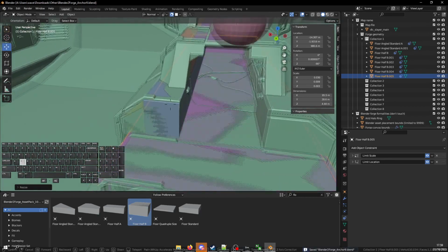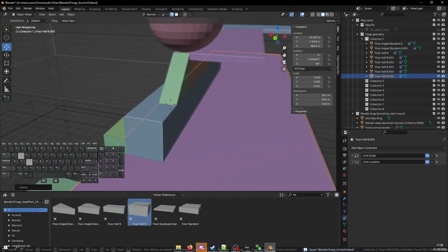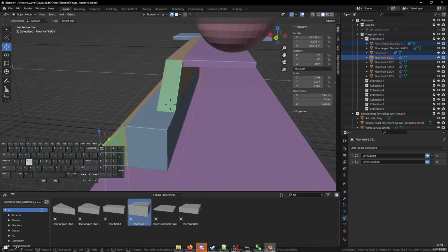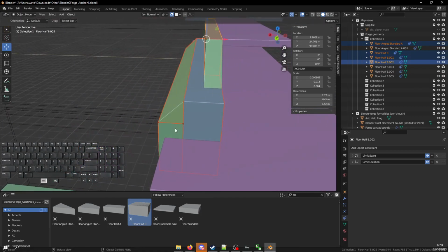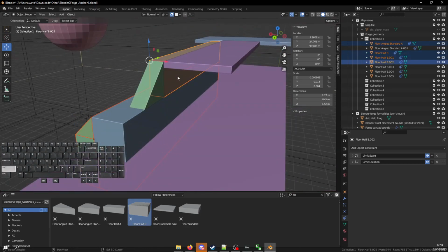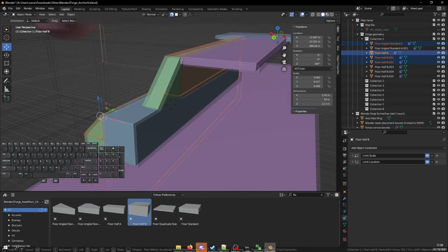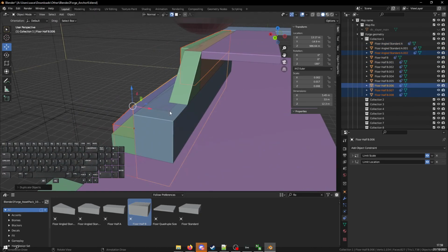Then let's duplicate this one side that we created to save some time. So we can duplicate at least these pieces here and then move this one a little. So I'm selecting multiple pieces by holding Shift. And the last piece you select is the origin piece for this group. So I'll select this one. Now Shift D to duplicate.